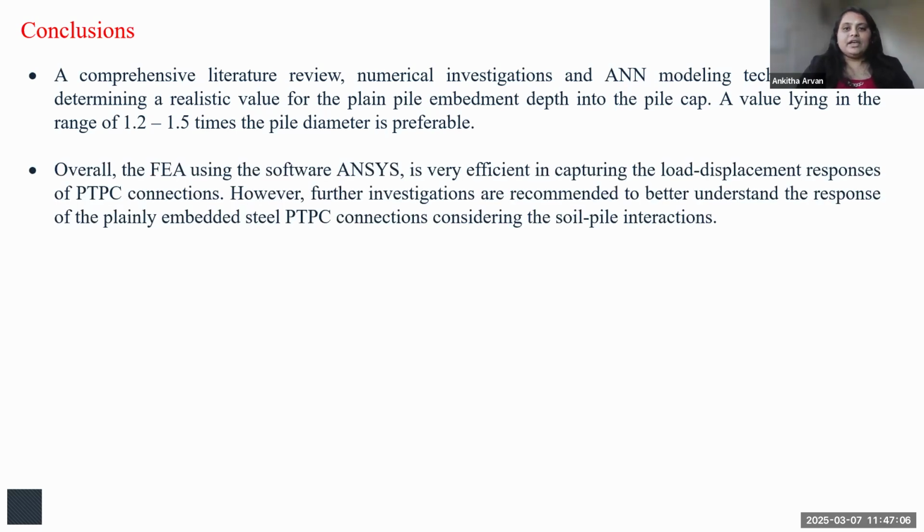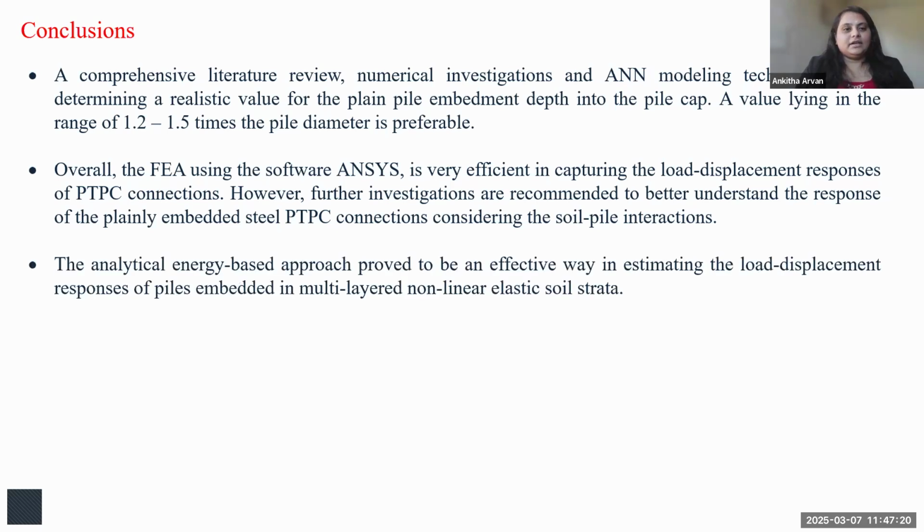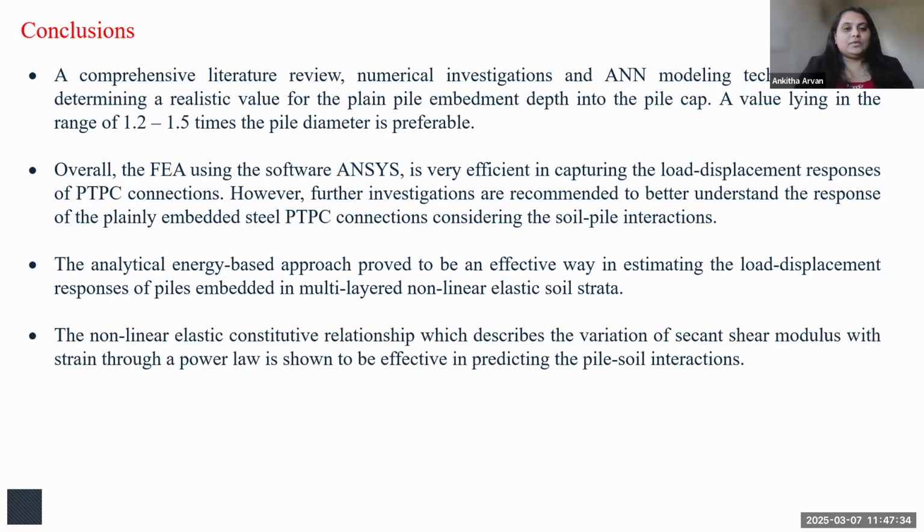Then using FEA was very efficient in capturing the load displacement responses of the connections. However, further investigations are needed to trace the response of steel PTPC connections, considering soil pile interactions mainly, because that was difficult to replicate. Then the analytical energy based method was an effective method to estimate the load displacement responses, especially when they are embedded into multi-layered soil and considering the non-linear soil model. And we also saw that the soil model was described in terms of varying the shear modulus through a power law. So that helped understand the pile soil interactions quite well.